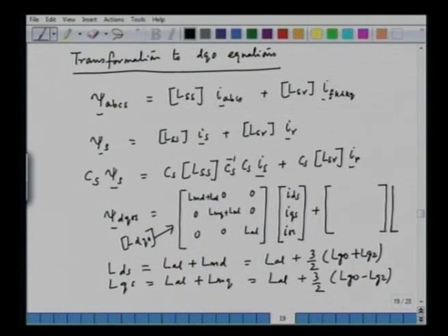So, we have the transformed currents here, IF prime, IKD prime and IKQ prime, and this matrix would be LMD, LMD and 0, and then 0, 0 LMQ, and then we have 0, 0 and 0. So, we have the inductance matrix referred in the rotor reference frame.